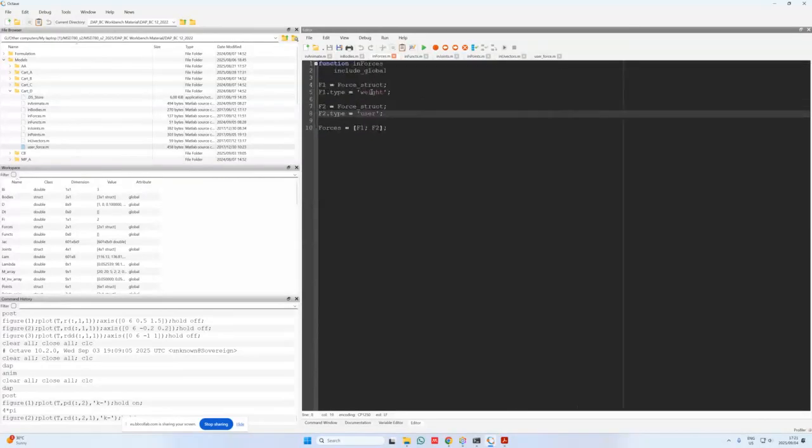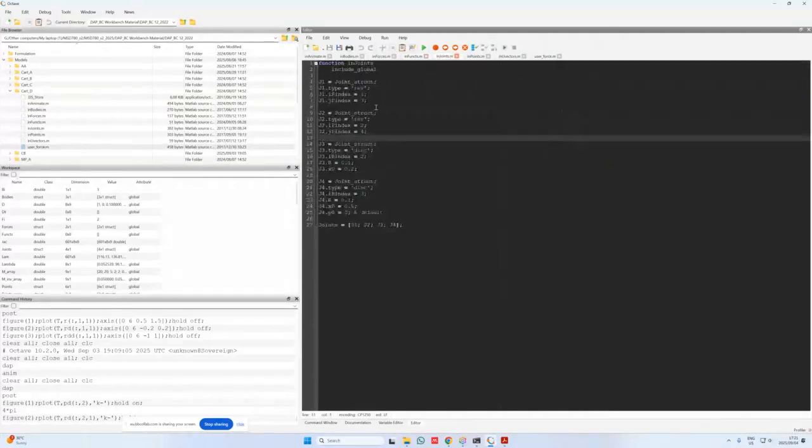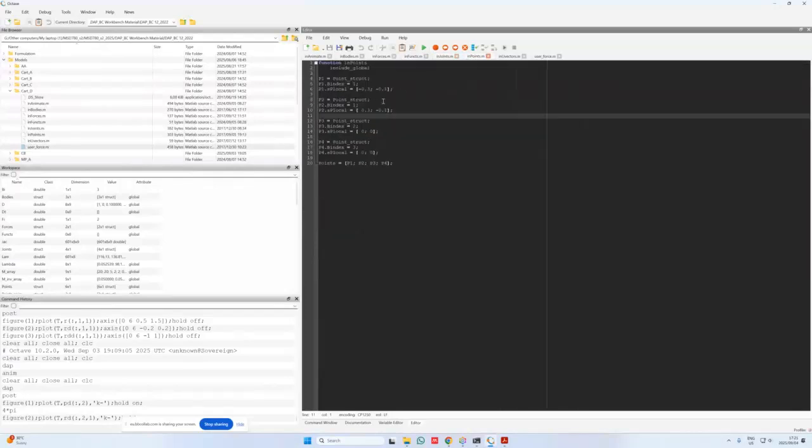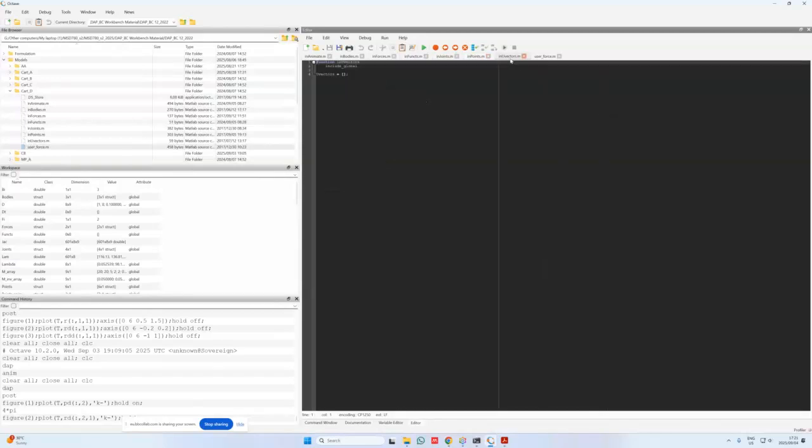In forces, we still specify weight and then a user-defined force. In functs is still an open list. In joints still consists of the revolute and the disc joints in the system. In points is the 4 points that I use to connect the revolute joints in the system. In U vectors, still an open list since I don't have any translational joints in the system.